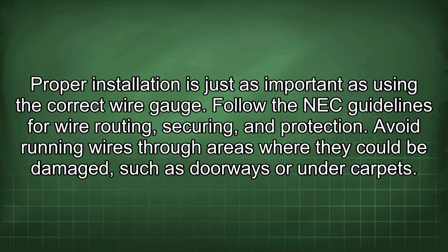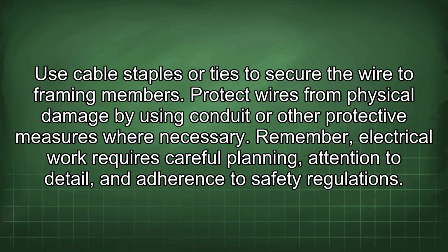Proper installation is just as important as using the correct wire gauge. Follow the NEC guidelines for wire routing, securing, and protection. Avoid running wires through areas where they could be damaged, such as doorways or under carpets. Use cable staples or ties to secure the wire to framing members. Protect wires from physical damage by using conduit or other protective measures where necessary.